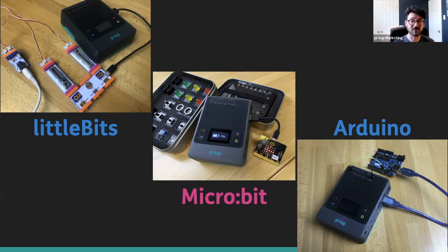Because this is powered by the Raspberry Pi 4, any project that you can do with a Pi 4, you can probably do with this unless there are size constraints. The pi-top has a battery, a speaker, all sorts of additional components, so it's larger than a Raspberry Pi. But if there's not a size constraint, like if you're just plugging a Sense HAT or a Waveshare screen or any sort of standard Raspberry Pi accessory in over the GPIO pins, you're going to be able to do that out of the box with the pi-top.